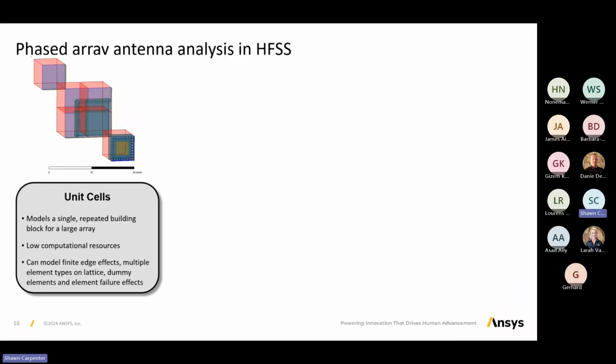Now, HFSS is particularly well known for a really great technique for capturing models of phased array antennas that are finite in nature. And when we model finite phased arrays, we're particularly concerned about mutual coupling effects as well as the edge effects and the corner effects, and also coupling effects on the array that come from radomes or other unusual structure close to the antenna.